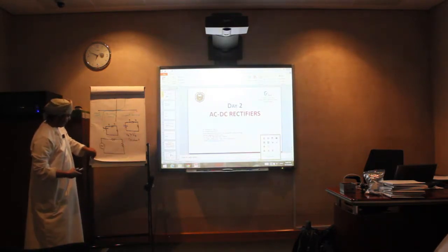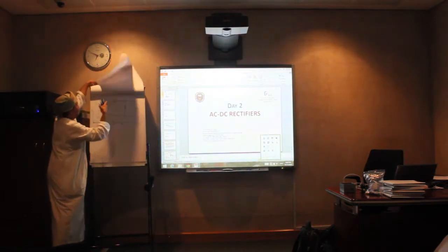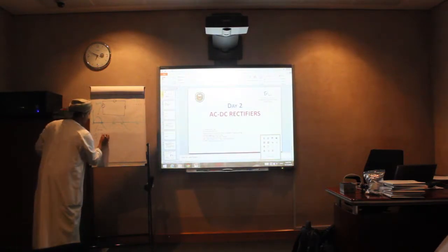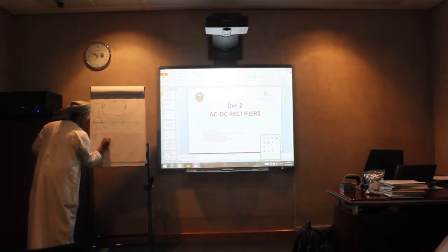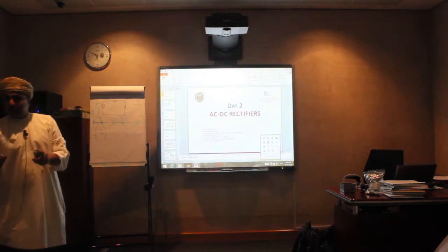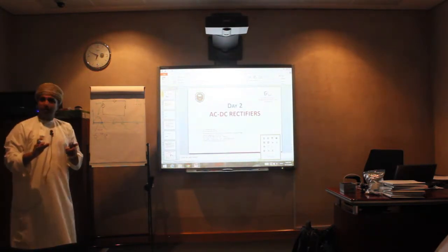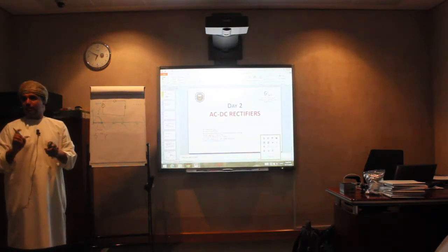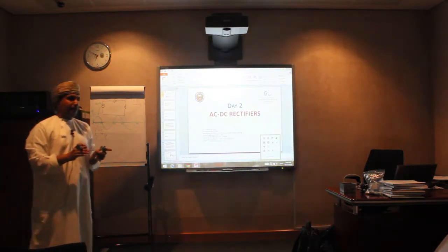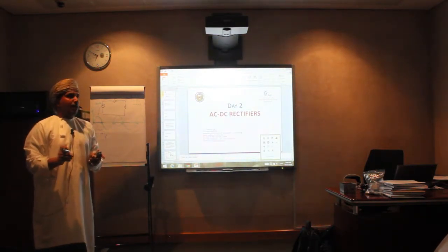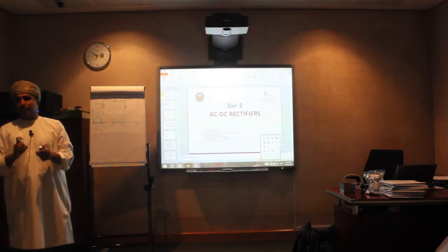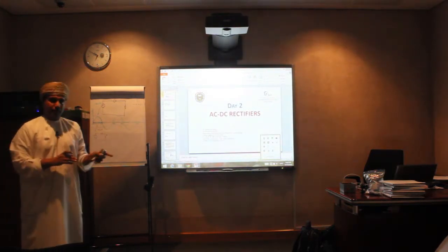So if this one will conduct, and I would like to measure the voltage across the load here. This one conducts, right? So if I assume just an ideal diode, that means when it conducts, the voltage drop is 0, right? But practically, it could be 0.7, and sometimes for power applications, you can find diodes with a voltage drop between 0.2 to 2 volts depending on the manufacturer.